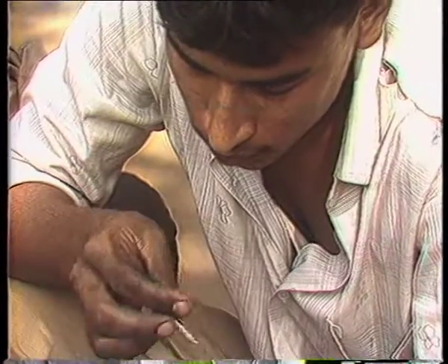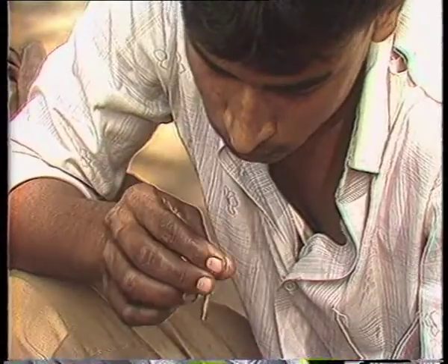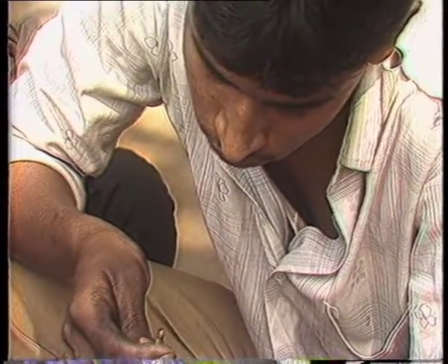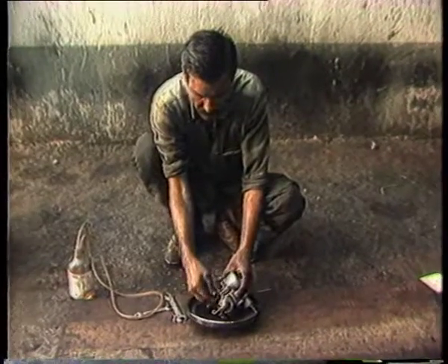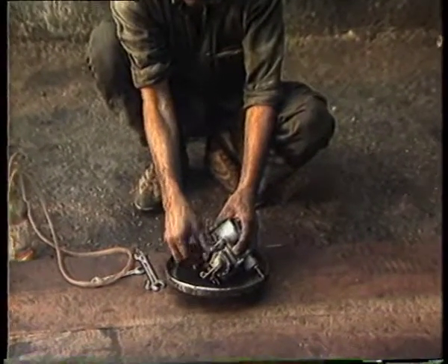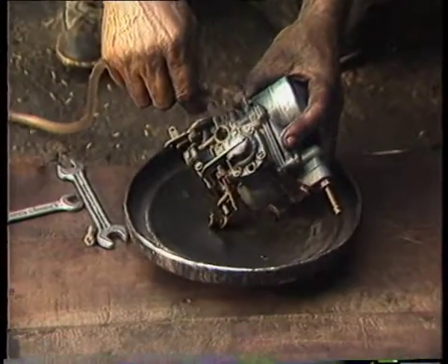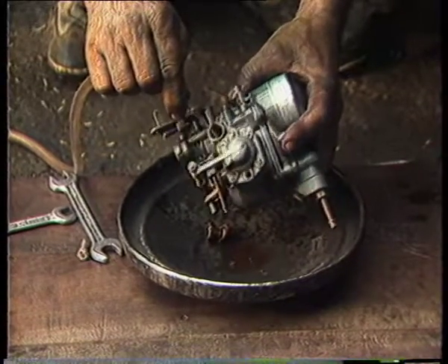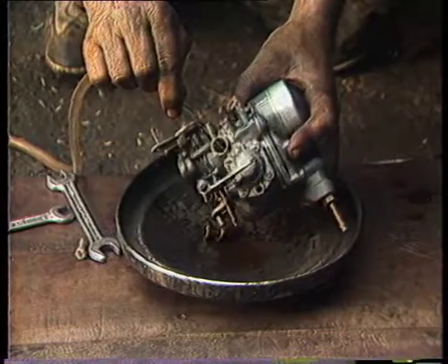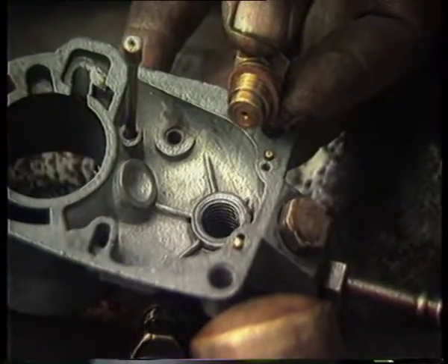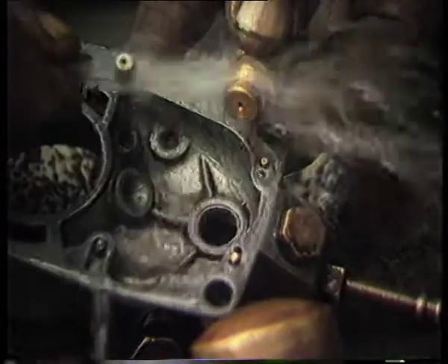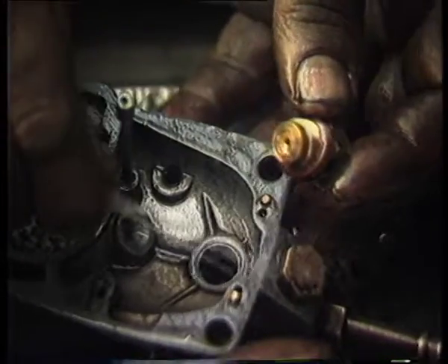In any case, to maintain the engine in smooth running condition, the carburetor should be regularly serviced as per the vehicle manufacturer's recommendations. The jets should be cleaned by blowing them out with air pressure. Never push wire through a jet hole, as this will damage the calibration. Passages can be cleaned out by removing the jet or jets from the passage and squirting a syringe filled with petrol into the hole from which a jet has been removed. Needle and ball valve assemblies can be washed in methylated spirits or petrol to remove sediment and gum.